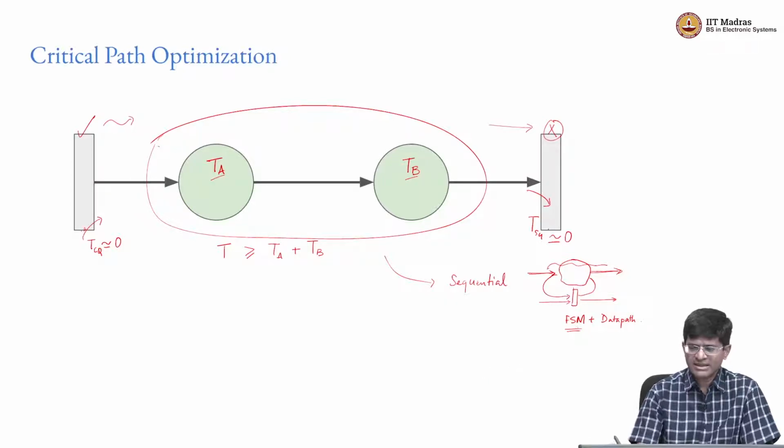The problem is, there is a finite state machine, which means that it's probably going to take me 2 clock cycles to actually finish the work, right. So it's not very clear that I could actually save time in order to generate a given output. But it may be possible that my entire circuit could run at a higher speed.